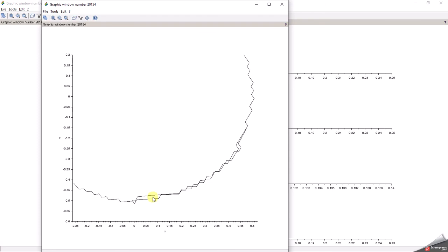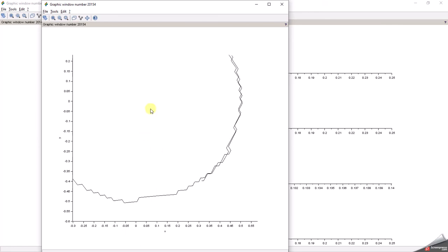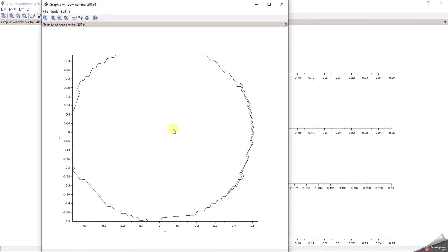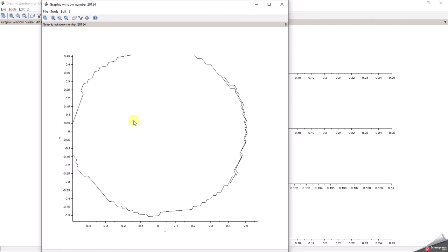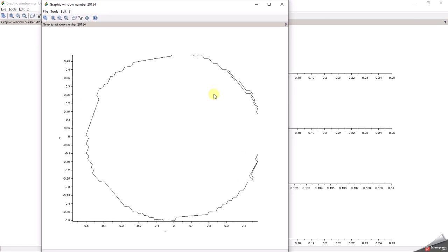So I had a hell of a time actually locking into the supply frequency of the motor. Okay, and I ended up using a phase lock loop. So a phase lock loop has a PID block in there, locking in. Well, it's locked in by now.